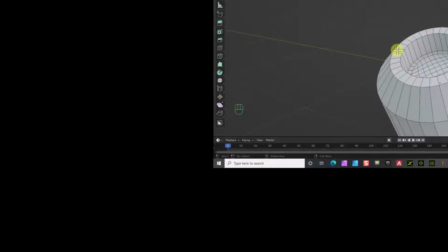That's that. I'm going to add some more detail to these edges, so Alt key, select this one with the Alt-Shift key. And go to bevel. A little bit of detail here. About 7. I'm going to add some loops. Bring it down low, a little bit higher. Basically add this throughout. Help define the object a little bit better when you subdivide it.